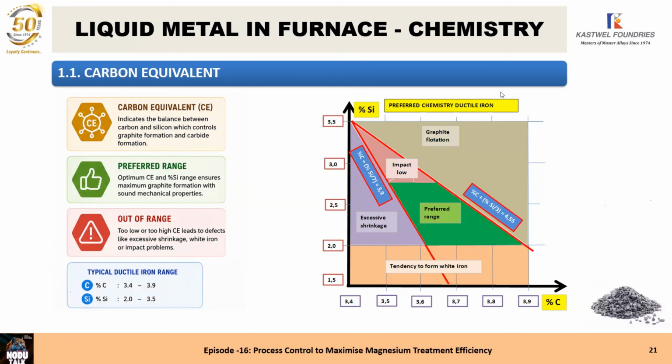It's very difficult. And one more thing, staff, when you have the in-mold process, the castings have high silicon, so the amount of returns that you can use in the subsequent processes also reduces when the returns of in-mold process castings are used. For sure. You can use nearly no returns then, because the silicon content must be so low that you cannot melt them again. And not melting your returns is a big loss for a foundry. And if you don't remove the slag by a good gating system in the in-mold process, your castings are likely to have slag defects.